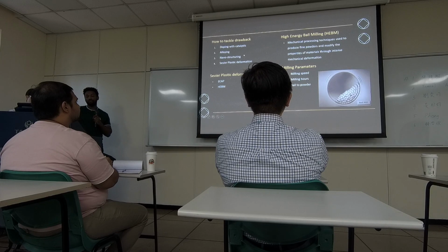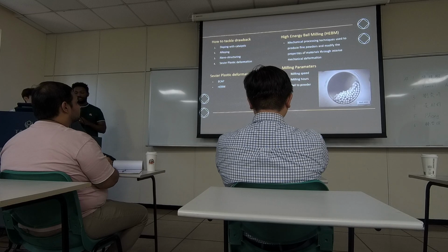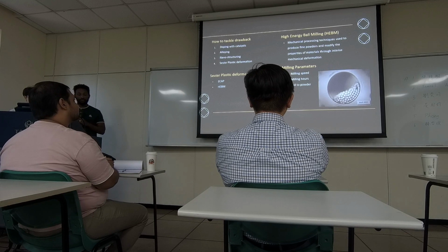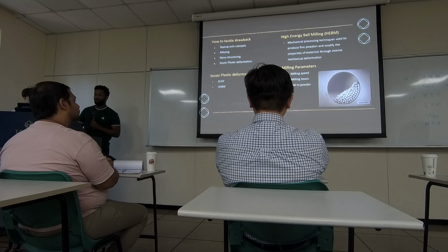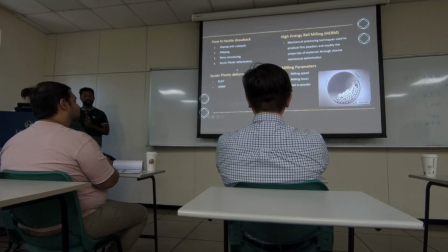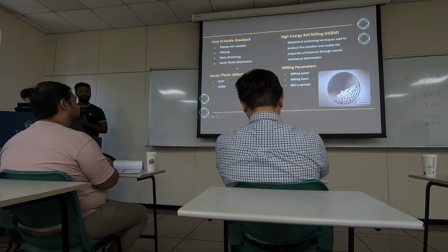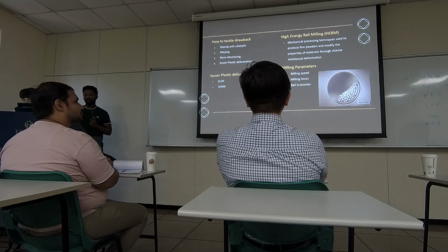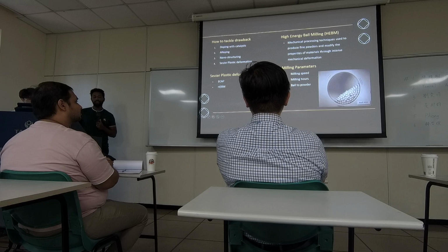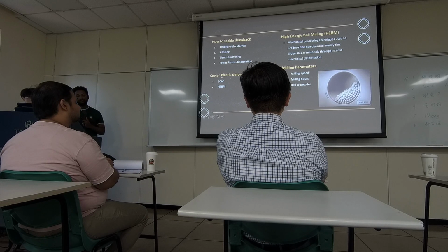Nanostructuring is also one solution. Altering the microstructure of the surface of magnesium will enhance the storage performance of magnesium. And the fourth one is severe plastic deformation. By mechanically deforming the material, we will induce fine grain boundaries and more dislocation density, and these properties are very good for storage performance. And today we are going to discuss the last solution, severe plastic deformation.